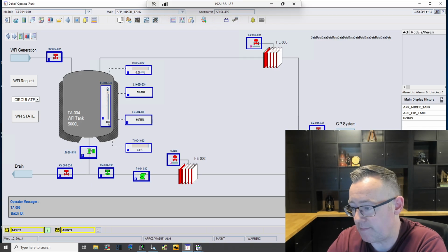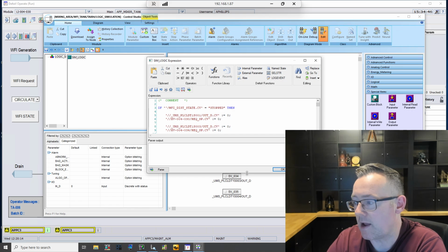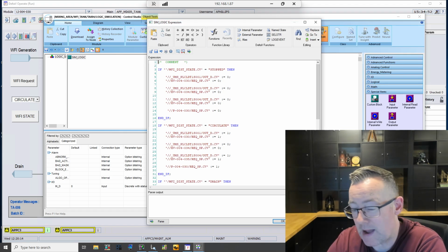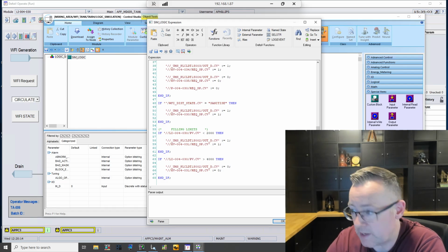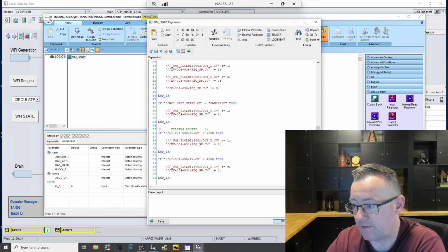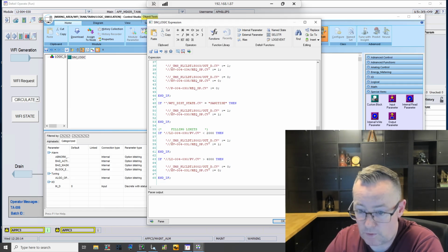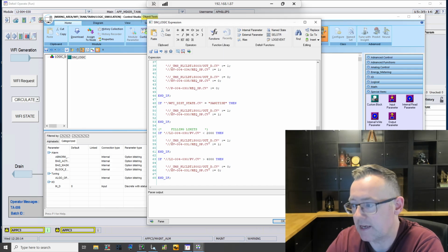The core thing is that when you're inside here, you can compare conditions. You can actually do a little bit of maths if you want to as well. Like here, for example, in terms of the filling. If the level sensor of the tank is less than 2000, then the filling valve will open. And here, if the actual level is over 4000 kilograms, or liters, sorry, in a particular tank, then the filling valve will turn off.